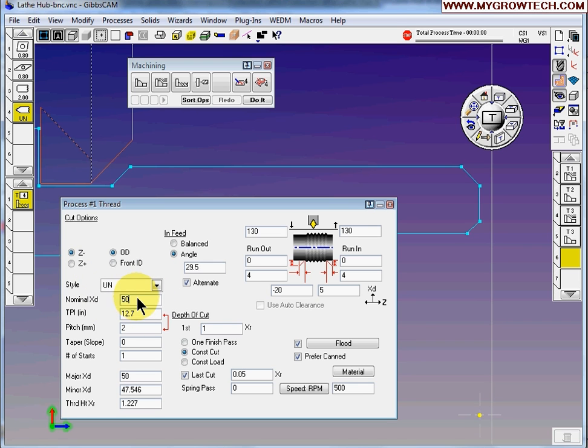You just select this and press the Alt key. When you press the Alt key on the keyboard, your mouse cursor will change from the arrow to a square box. But in this movie, I don't think you can see it. But you can see it on your software, not on the movie. So just select, make sure you press the Alt key, select this point here to update the value to nominal diameter 39, pitch is 2.